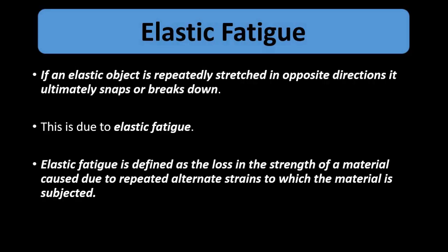There is a breakdown in the elastic material because it ultimately loses its strength because of the alternate application of stress. This results in alternate strains in opposite directions. That's why there is loss of strength in the material, and the material finally breaks down.